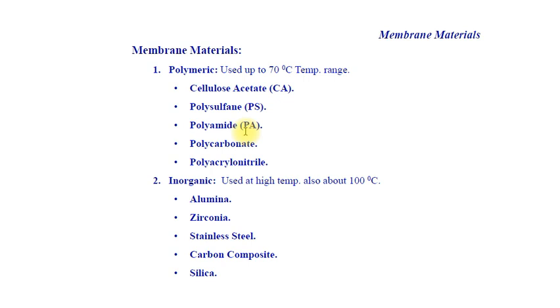For ultrafiltration, where you want to separate particles, you can use polysulfone membranes. Polysulfone ultrafiltration membranes are also used as a base or support for the polyamide or cellulose acetate reverse osmosis membrane. Why? Because polysulfone has very good mechanical strength. So basically polycarbonate and polysulfone membranes are used in membrane processes because they have good mechanical strength.